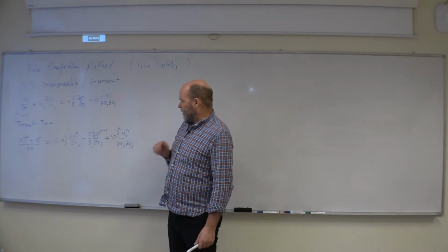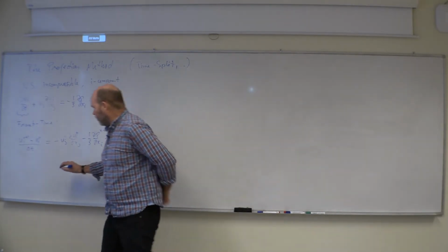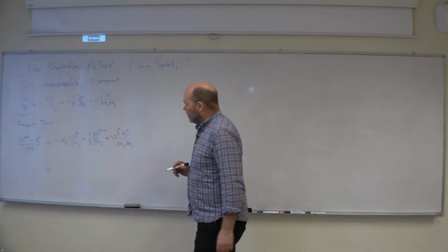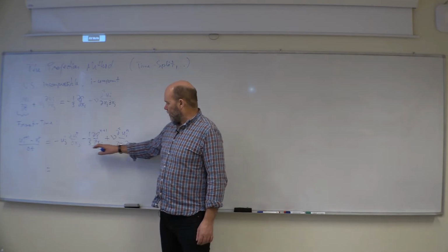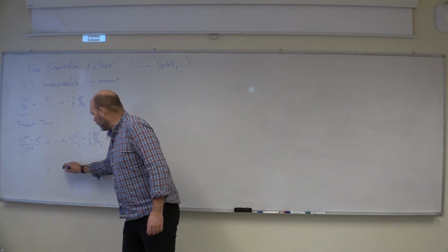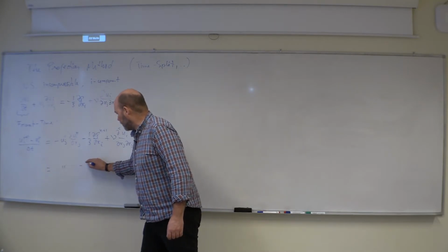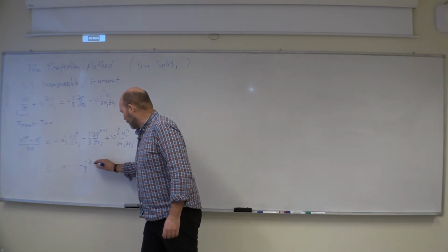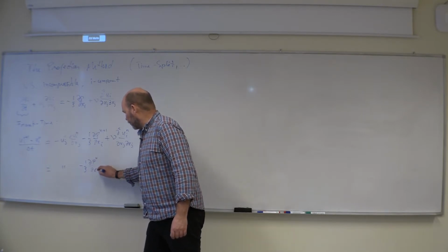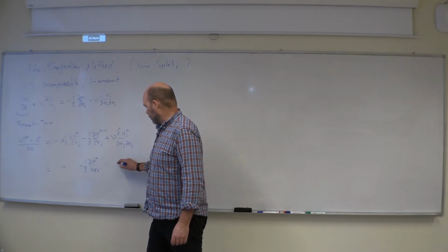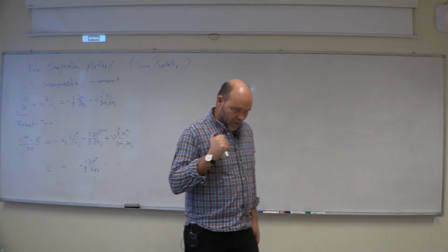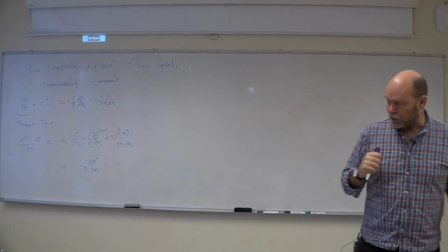Let us skip this part. So if I rewrite this one, I write the right hand side exactly the same except the pressure term. There I now write it as it was first, time level n, dxi, and then plus this term. And then I say, okay, I don't have the new pressure, so I use the old one.